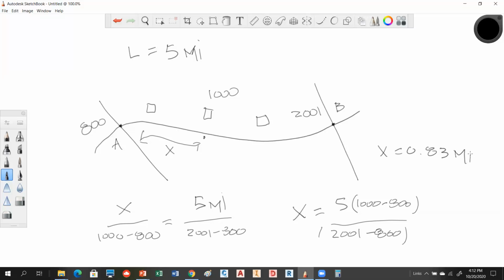So basically, the system would come down that distance and put the point there, and you might actually get the spot here as opposed to where the house is, okay? Because the actual distance and what the linear interpolation gives you could be two different things. Does everybody kind of get the idea? Particularly in rural areas, that's going to be more of an issue. In an area where you have lots of houses, with parcels of maybe 100 feet, you're going to get a pretty true location. But because this can happen in rural areas, you can be a couple of 100 feet off from where the actual true location is.